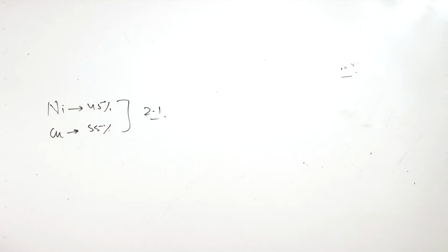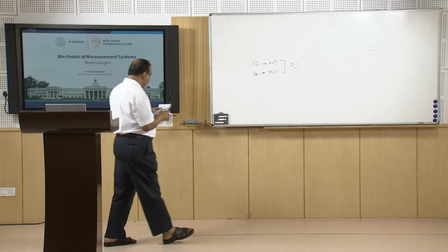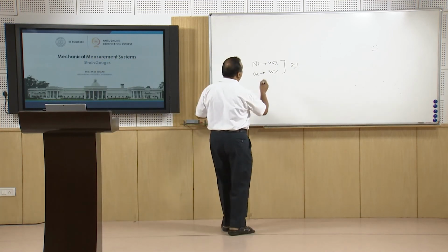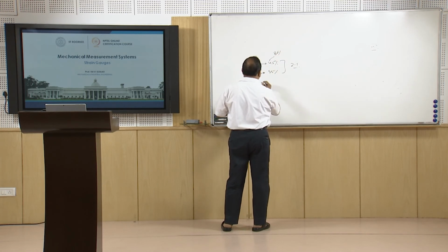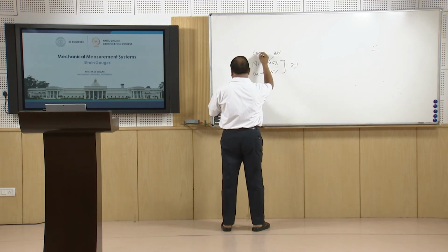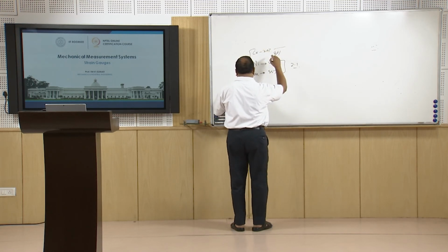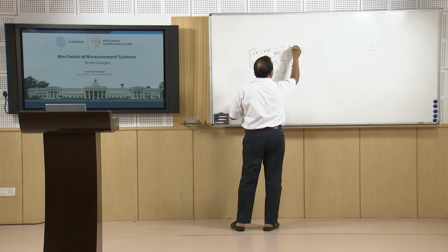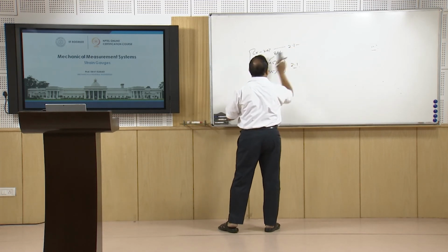For metals and alloys, if you change the composition, for example nickel 80% and chromium 20%, a nichrome alloy, the gauge factor is 2.1 to 2.63.